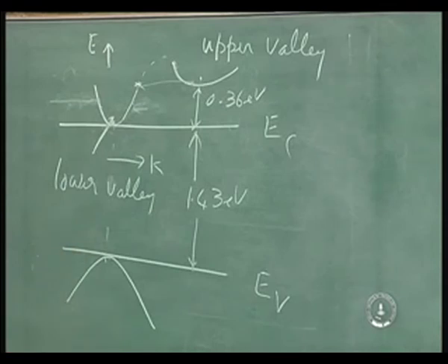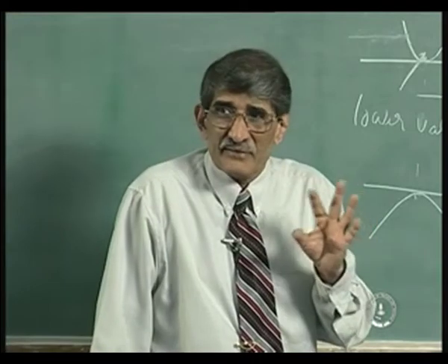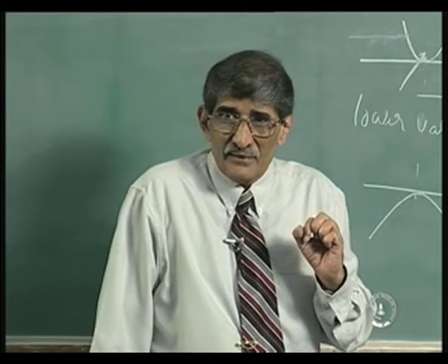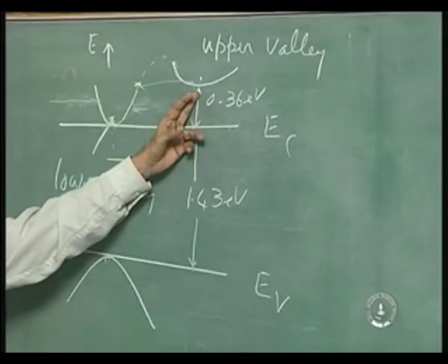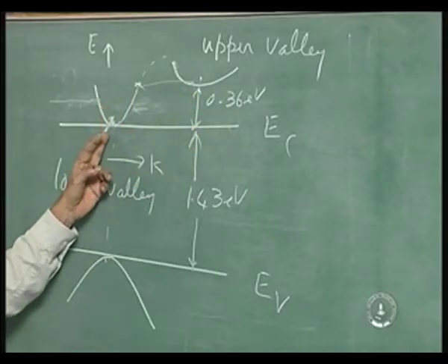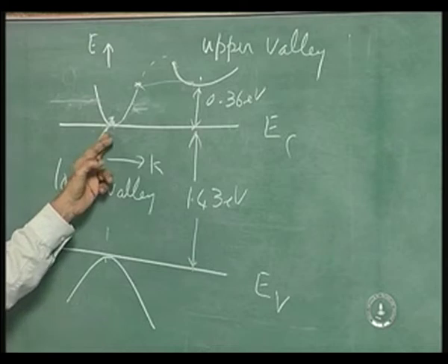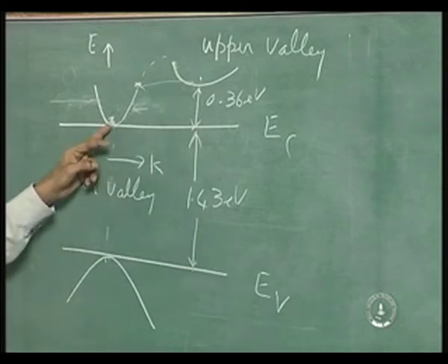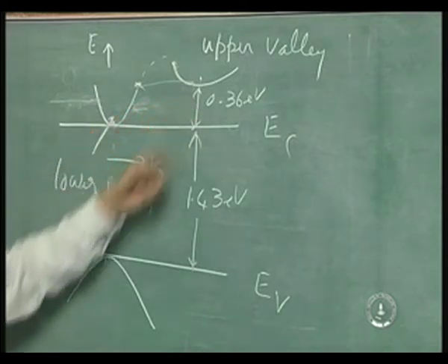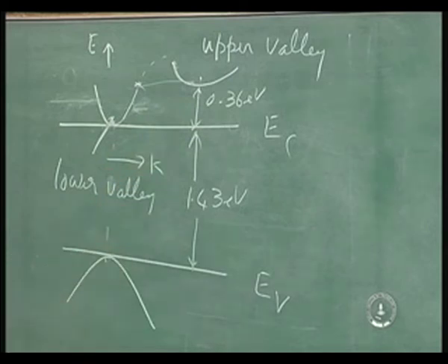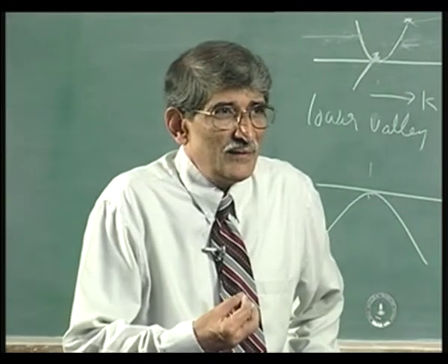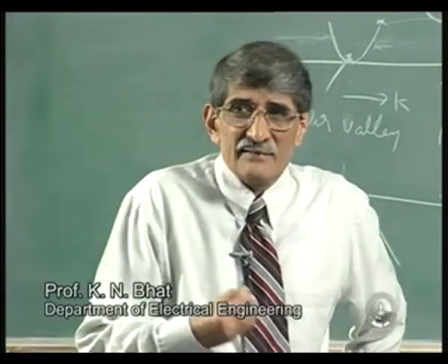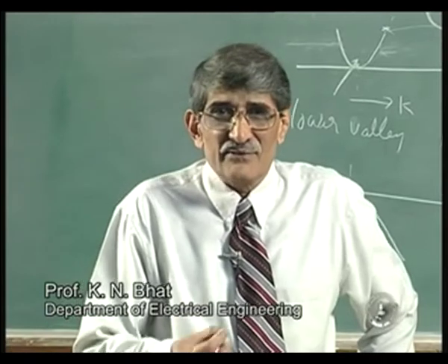Okay, this is a very oversimplified thinking, which sounds quite good from the physical consideration point of view. In terms of the energy band diagram, if you want, you can throw in further jargon: electrons get scattered from this valley to that valley. Why do you say scattered? Its mobility falls. Whenever there is a mobility change, you say it has scattered. So it is called inter-valley scattering. It is the jargon which is put up.